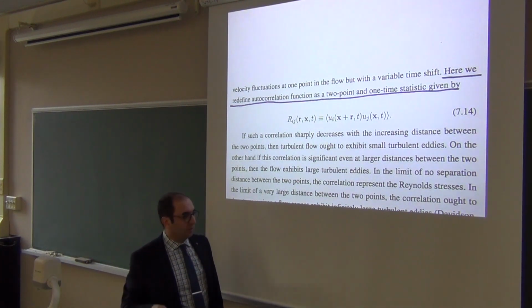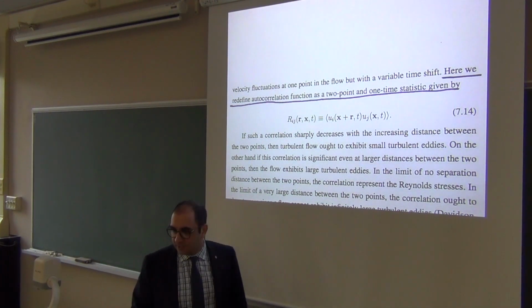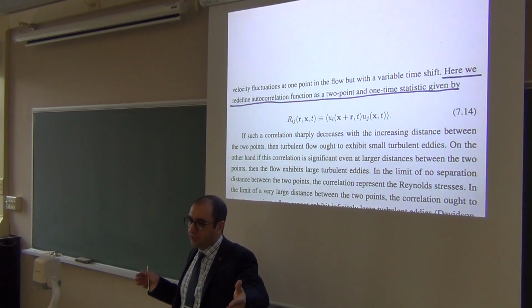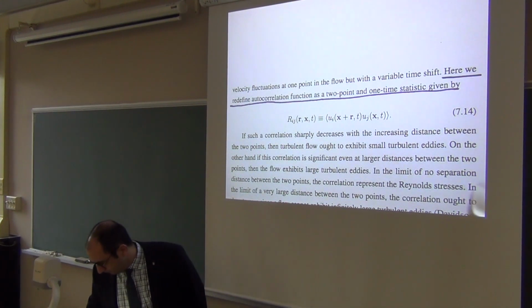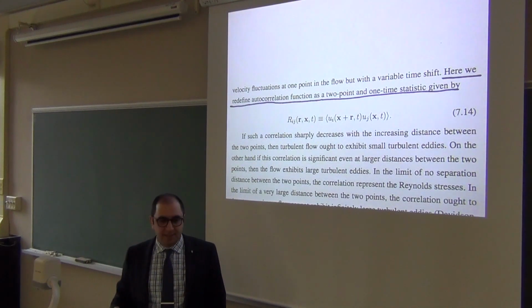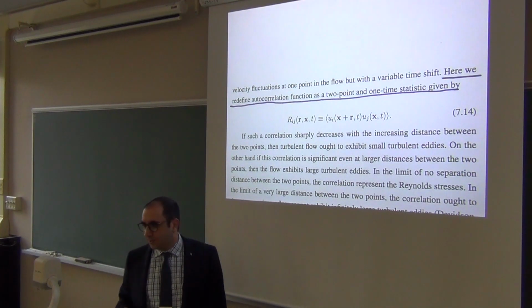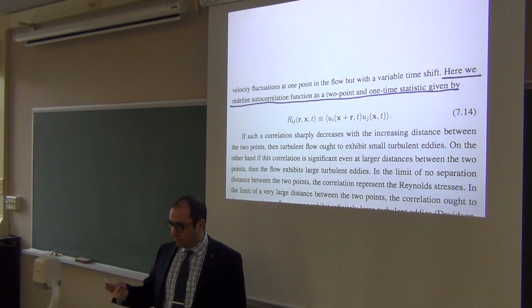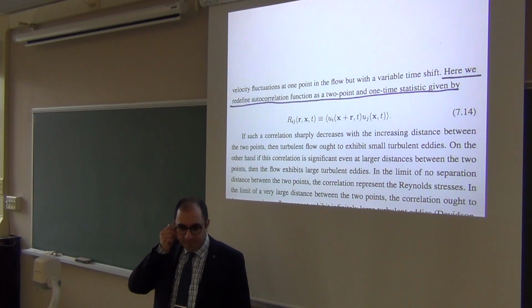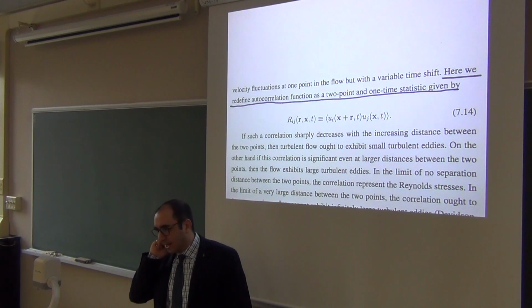So if I repeat this indefinitely, then I can calculate a sort of an ideal mean for these correlation of these two fluctuations. Of course, in practice, pure ensemble averaging is impossible unless you're doing modeling, because you can repeat an experiment in the modeling world. But yeah, you would do time averaging in practice.